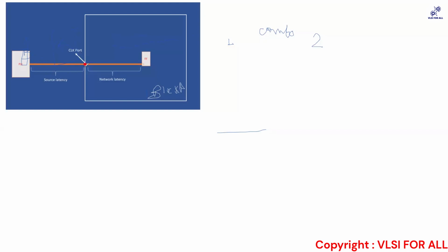But understand that since your design has not reached the CTS stage, you need to model something, correct? I know once my design is ready, it might take, let's say, 10 ns to reach my clock signal from this clock port to the clock pin of the design, correct? So that delay you are terming as network latency.